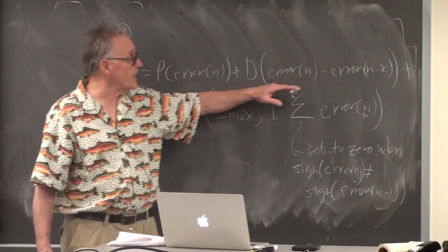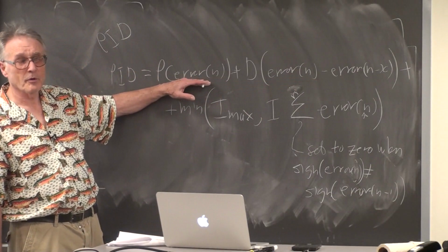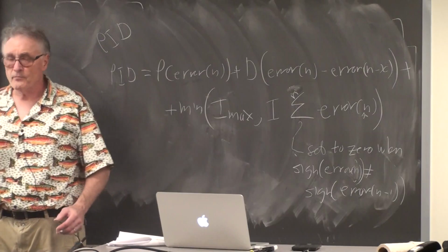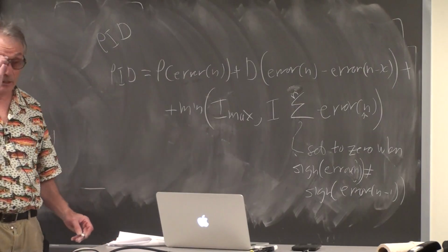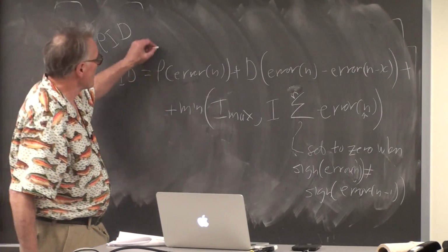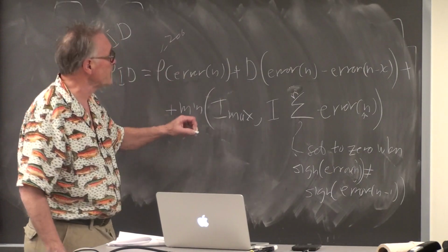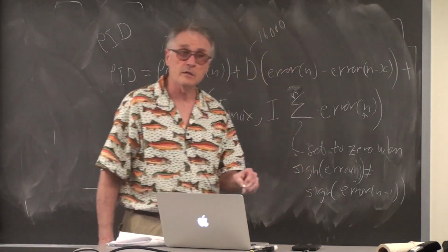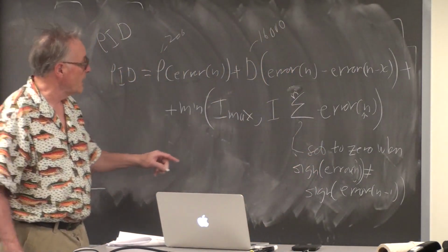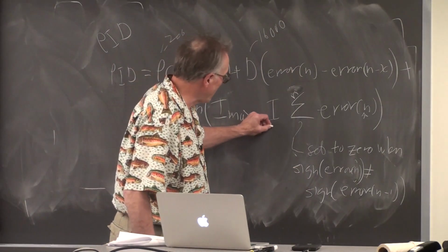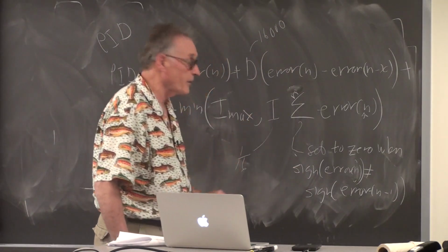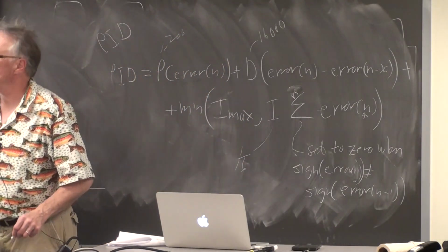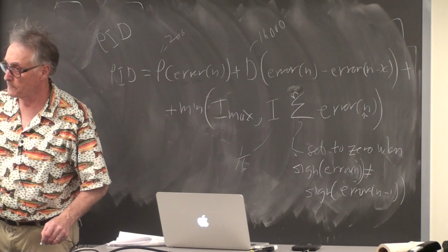So this term is going to compensate the proportional term at high gain. And the integral... For example, in the units I chose for this simulation, P had a value around 200, D had a value around 16,000, and I had an amplitude of about 1/16. So the integral term is small in terms of the total contribution.